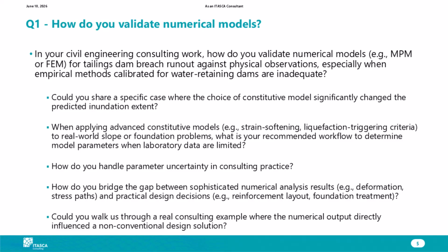So I tend to rely mostly on in situ tests, and specifically, when it's possible, the cone penetration test. In my opinion, when you have those kinds of soil, the cone penetration test is an invaluable tool to evaluate the interference or the interaction between different layers of different permeability and different consistency. So you can better estimate the time scale, and you can better estimate the response of the soil at the larger scale. The lab test is very narrow, very limited, so you cannot really consider any kind of spatial variability in any way, shape, or form.